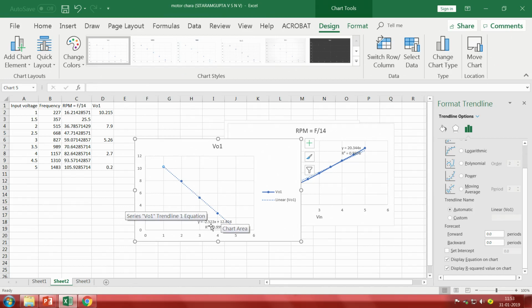The reason we are getting a negative slope is that, from the analysis we have already seen, the output from the monostable multivibrator as well as the integrator pulses will always fluctuate from plus 15 to minus 15, and the time duration of minus 15 is higher compared to that of plus 15 volts.